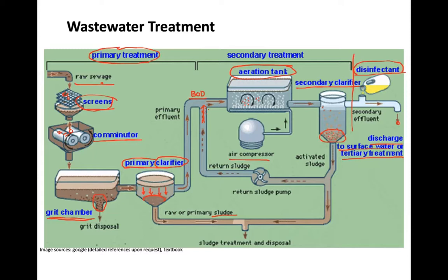Because we basically culture them in this aeration tank here. So their population grows a lot to form these larger solids. But if you imagine at the beginning, we have to introduce some bacteria into the aeration tank, right? So what that means is we can split a fraction of this solid, what people call activated sludge.